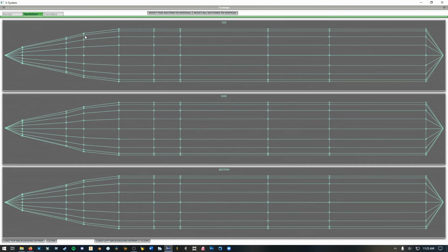So if you want to make a cockpit sort of shape, you can modify points in here as well. This is kind of useful if you want to smooth things out a bit or give yourself a bit more detail. So if I wanted to make a cockpit sort of shape, I can just raise up this here, over here, maybe. It kind of looks like a cockpit.